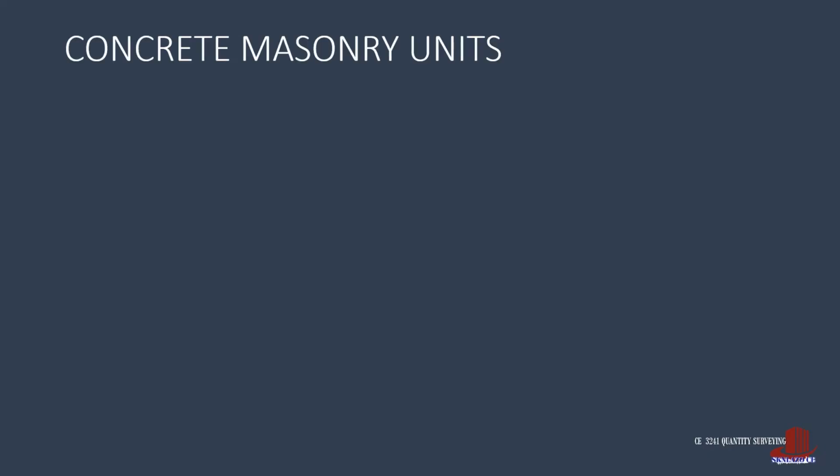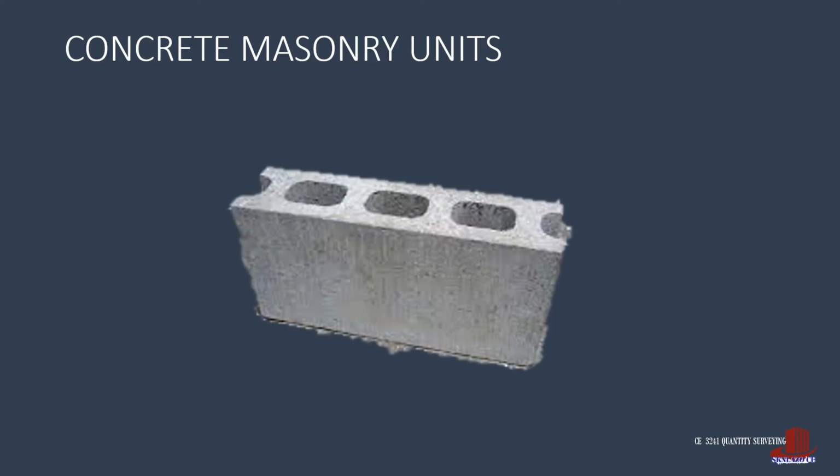From construction materials and testing, the standard dimensions of commercial hollow blocks have been discussed as 16 inches or 0.4 meters length by 8 inches height, or that is 0.20 meters. The only thing changing is the thickness of CHB, which ranges from 4 inches, 5, 6, or even 8 inches, the choice of which depends on the function of the wall or partition.